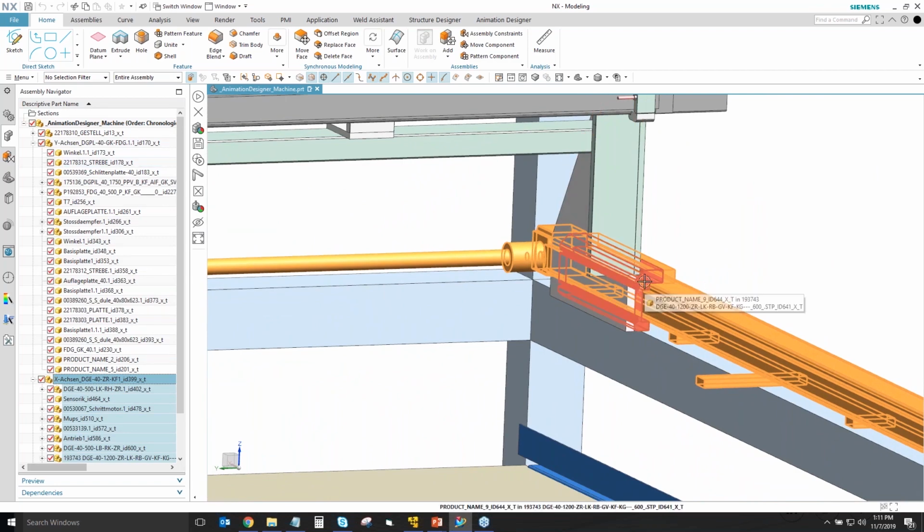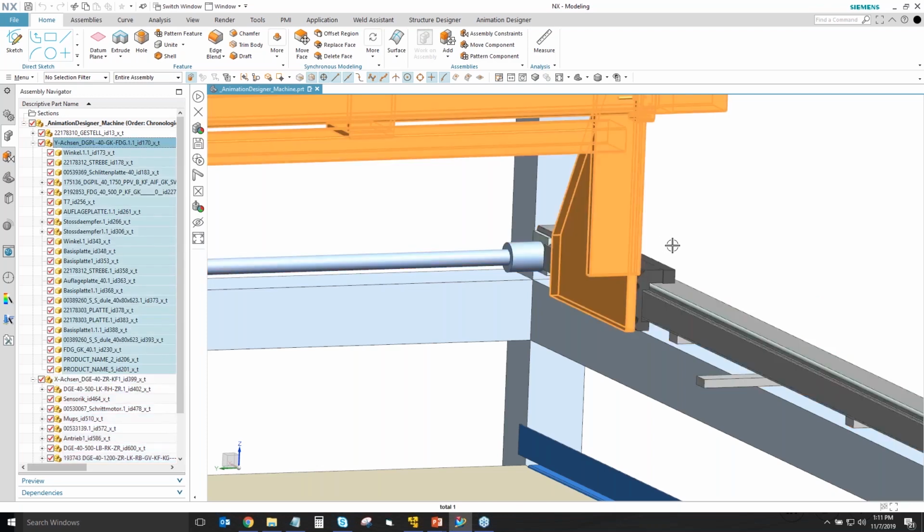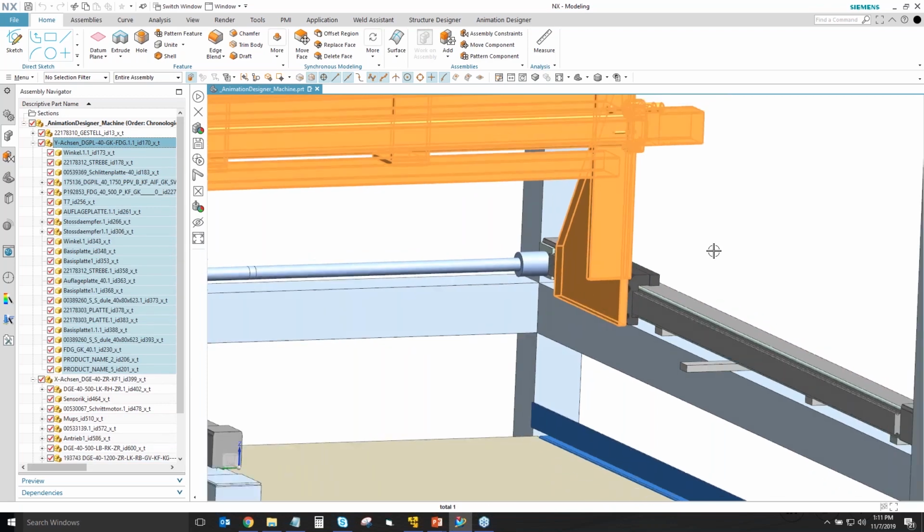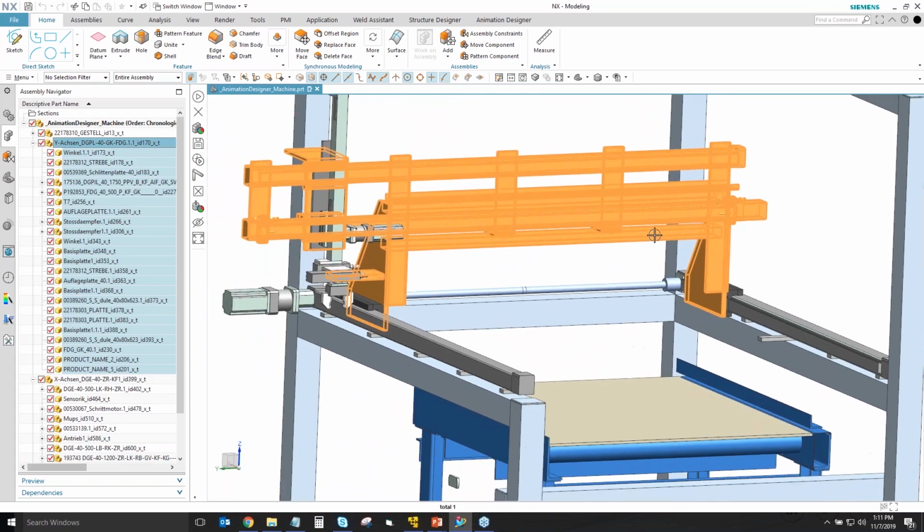These little components here that I'm highlighting in red should have been part of this other sliding mechanism, so when it goes back and forth, these guys come along for the ride, but they're not. They're going to stay fixed to this other part down here. This orange component that I have highlighted, I want these parts to be all part of it. Now, I don't know where they are in the subassembly, and I don't care where they are in the subassemblies. I'm just going to move them the way that I want to move them.